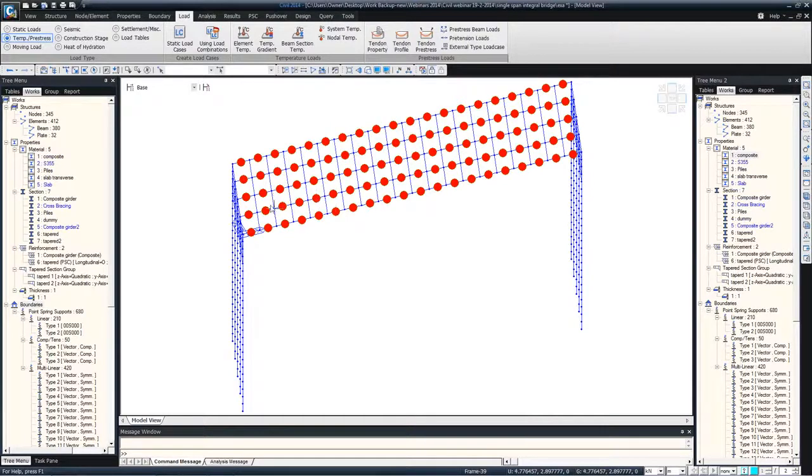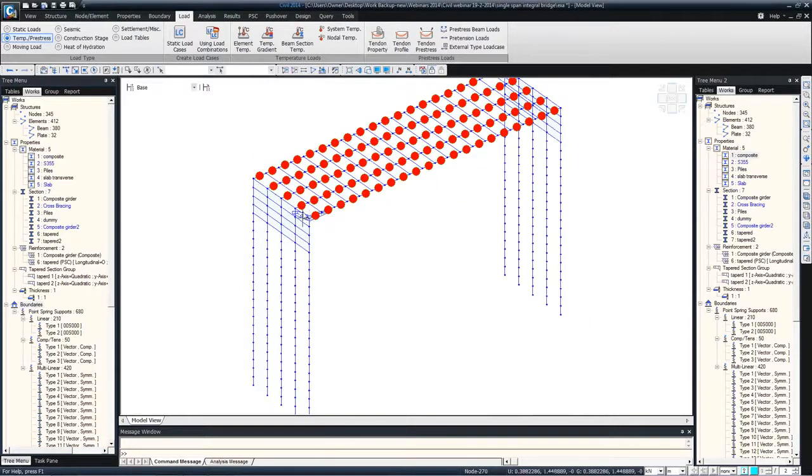If it is a grillage model, then we can go for some dummy beams modeled here, just to represent the extent of the loading. You can create some dummy beams in between with some little stiffness or smaller cross sections like 10 millimeters by 10 millimeters, for example, and just apply the loads as a floor load on those members.